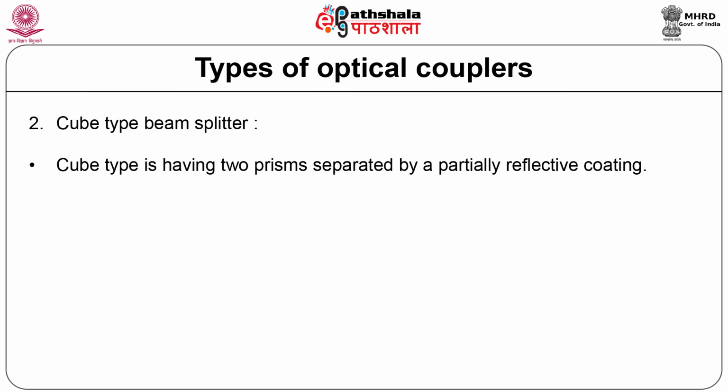It is important to note that a beam splitter cannot be employed by itself for dividing power among fibers. The presence of the splitter in the path of light is equivalent to a gap, which provides large losses for the diverging rays emitted by the input fiber.